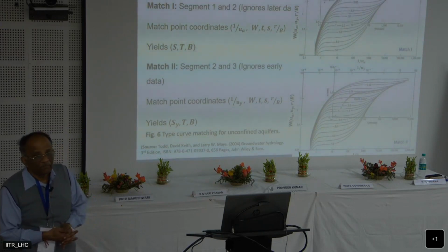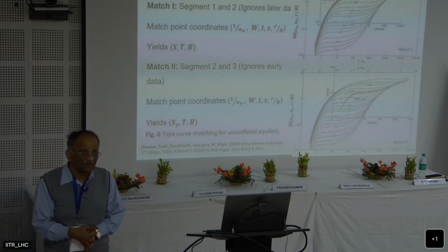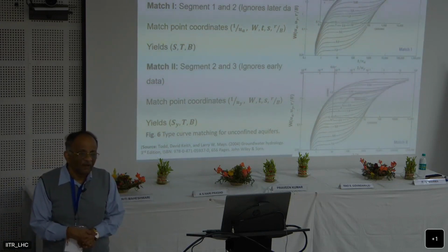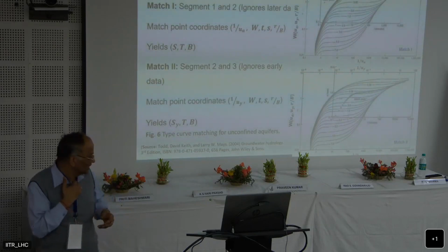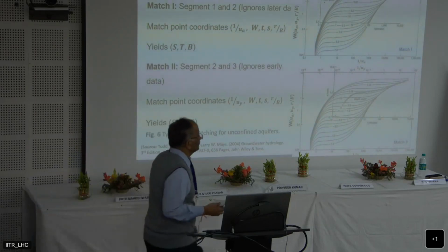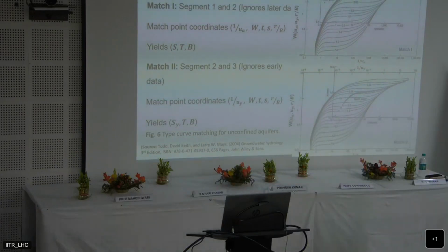What is meant by alpha? When we write it, we write Sy times e to the power minus alpha t. What we are saying is that the ultimate value of water released will be Sy, but that will be delayed; it takes time. So we express this as e to the power minus alpha t.